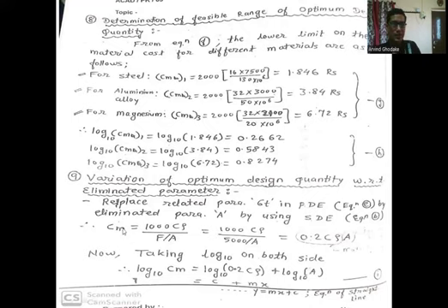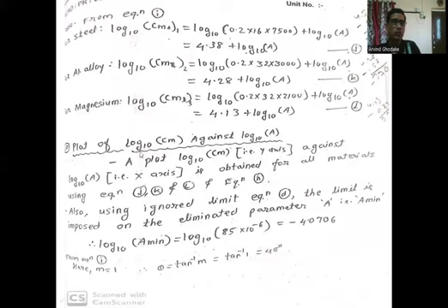So here our secondary design equation, Cm is equal to 1000 C rho upon F upon A, so that will be 0.2 C rho A. Taking log on both sides, you will get this equation in the form Y is equal to Mx plus C. We are developing the same equation for three materials, that is steel, aluminum alloy and magnesium alloy. Then plot log to the base 10 Cm against log to the base 10 area, meaning we are plotting the cost to be minimized against the area.